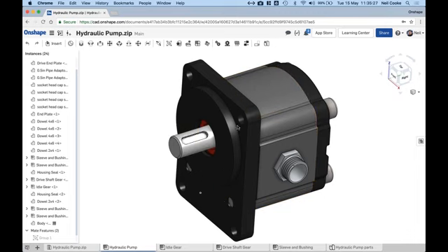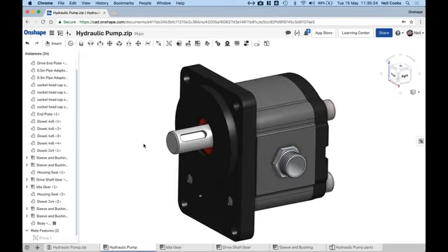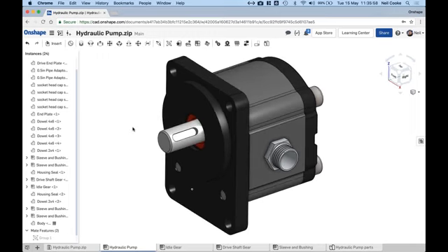Okay, so it's possible to do those relationships in the assembly using the assembly mates. Now, the assembly mates, as you saw there, are different from what you are familiar with in SolidWorks. Rather than create individual mate, align, insert, offset mates, they're done in one command. So in this case, it's a revolute or a fastened or a cylindrical or a planar mate. So there are a lot of single command mates which will do the same thing.